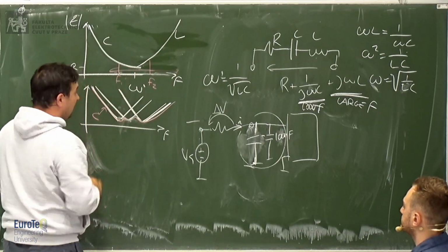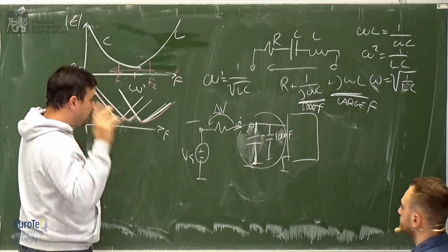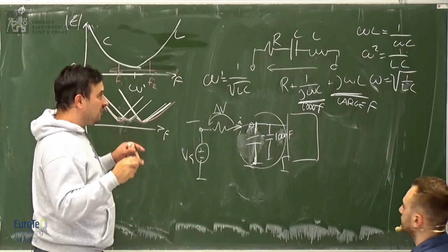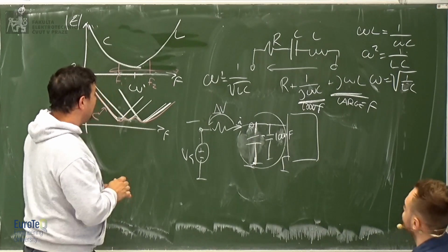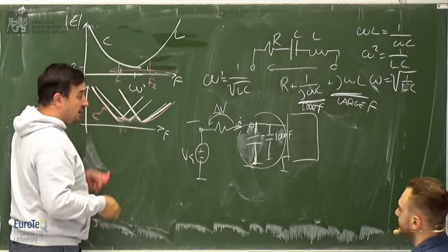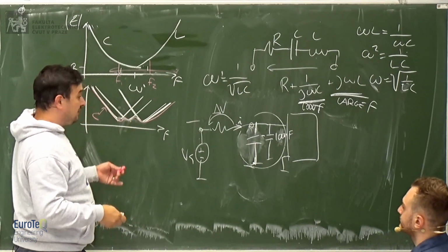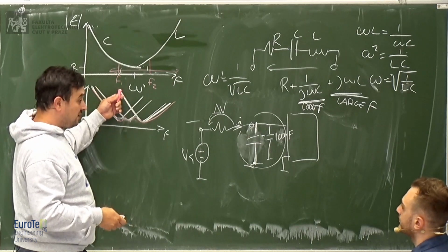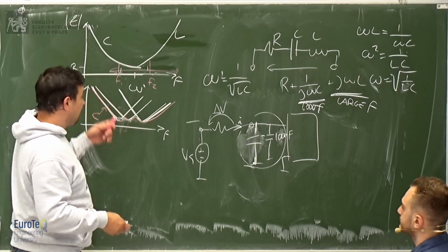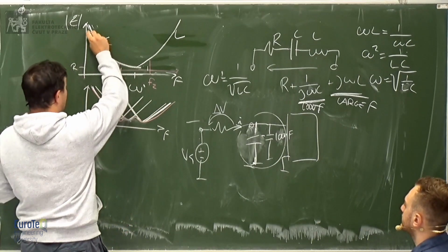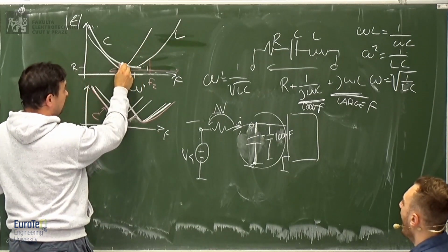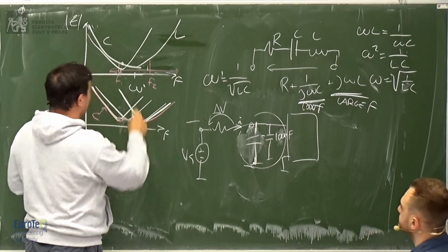So what I do is add extra selective short circuits, also for other frequencies here and here, by using multiple capacitors which have different resonance frequencies, for different values of resistance, capacitance and inductance. So I will have another which goes here. This frequency is not suppressed by the first capacitor, but is suppressed by the other capacitors.